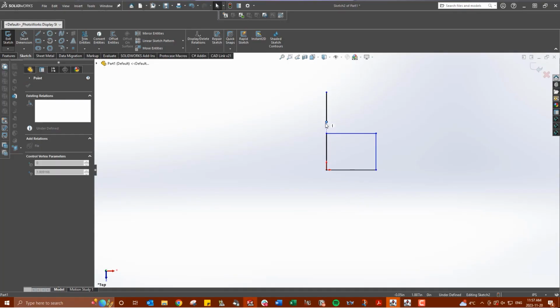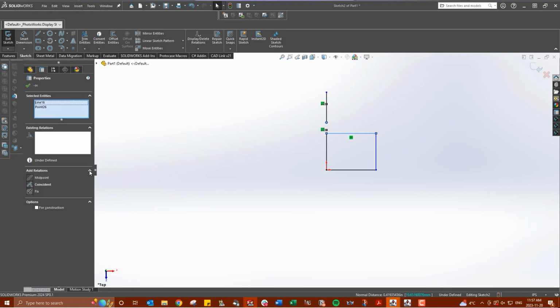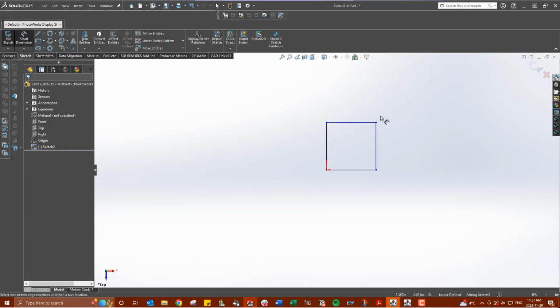This constraint works as kind of a snap point. It will allow you to pick one piece of geometry and make it snap to another. A reminder here, if the snap point location itself is undefined, it will require another dimension or a constraint. Think if you try and snap the end of a line to the section of another line, unless it is perfectly defined where that snap location is, it will still be floating.